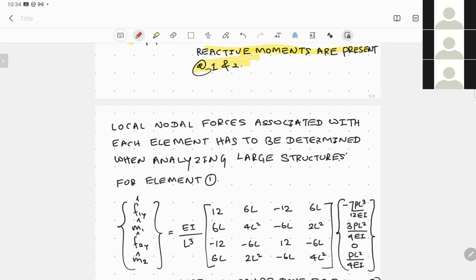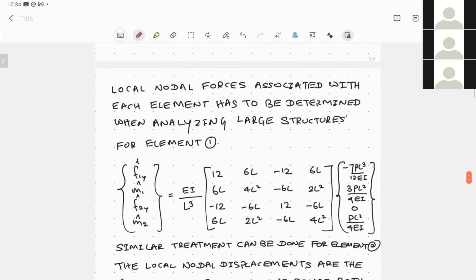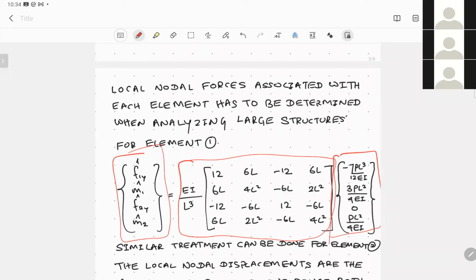Okay. So what you do in that case is simply extract the element stiffness matrix for a particular element and relate it to the corresponding nodal degrees of freedom. Nothing new. Here I have used the hat sign as well as simple letters, since we already zoom into the element level, where we move into the local coordinate system as well as the local forces acting within an element.